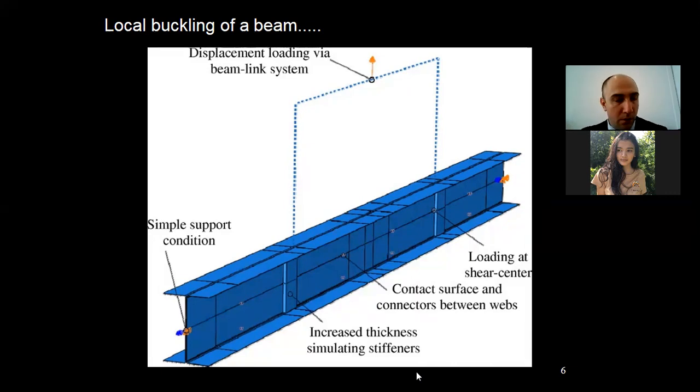But for an open section, the twisting mode is more flexible. Hence the beam both twists and deflects laterally at failure. This mode is well known as lateral torsional buckling. For a wide flange section with a higher lateral bending stiffness, the deflection mode will mostly be twisting in torsion. In a narrow flange section, the bending stiffness is low, and the deflection will be closer to the lateral buckling deflection mode.